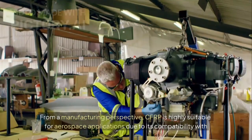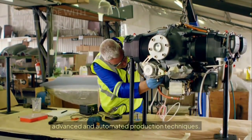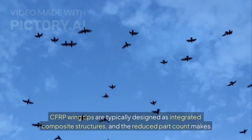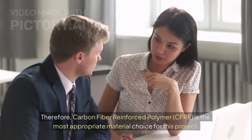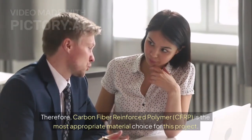From a manufacturing perspective, CFRP is highly suitable for aerospace applications due to its compatibility with advanced and automated production techniques. CFRP wingtips are typically designed as integrated composite structures, and the reduced part count makes CFRP wingtips highly suitable for automated assembly environments. Therefore, carbon fiber reinforced polymer, CFRP, is the most appropriate material choice for this project.